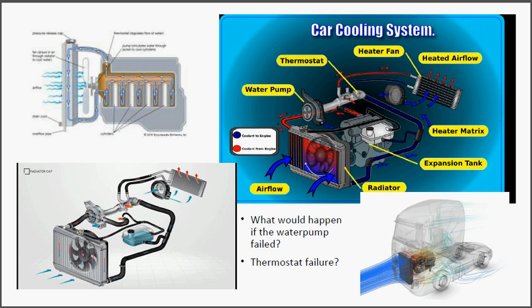If it's wide open, and I've experienced this once, I had a problem on my car where the thermostat was permanently locked. I couldn't do anything, I didn't have any tools. I called out the recovery service, and the AA guy came, and all he could do was take the thermostat out and put the thermostat housing back together. So I took the thing out, put it together, and the car worked again.